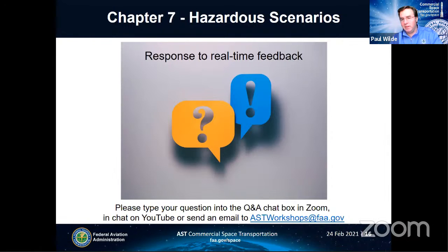Hey, Eric, I'd like to add to that answer. So the FAA has done some testing where we looked at impacts on aircraft, and we saw that at the 300 gram level, it's possible to defeat primary structure. And so that's a very key threshold for aircraft vulnerability that's grounded in some test data.